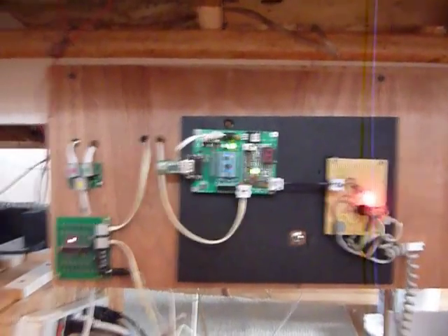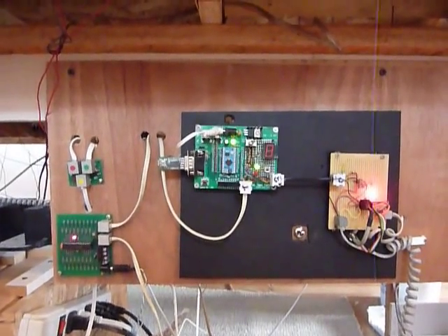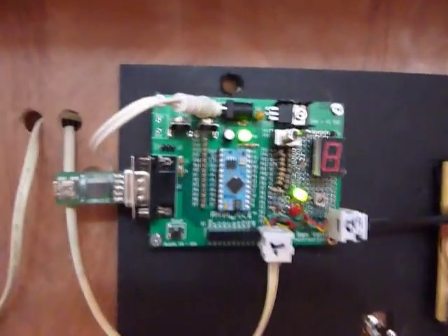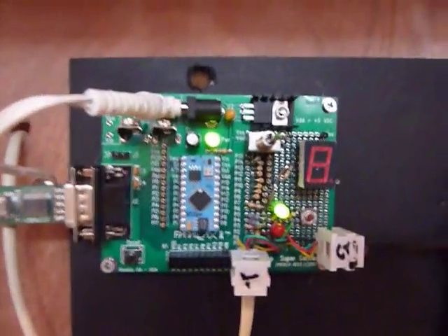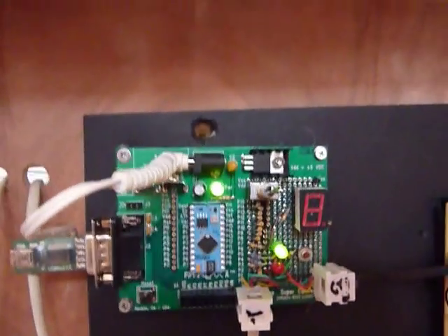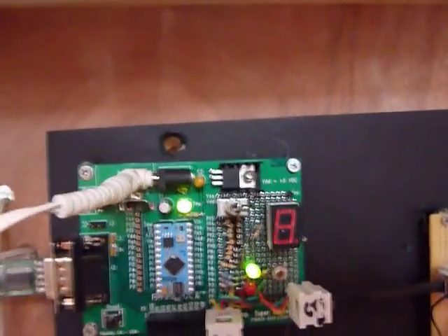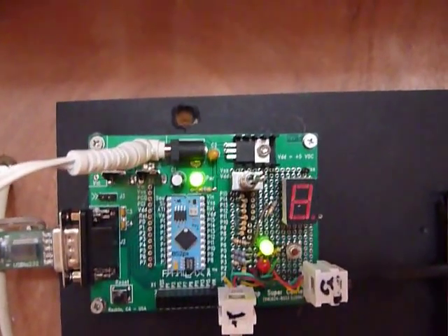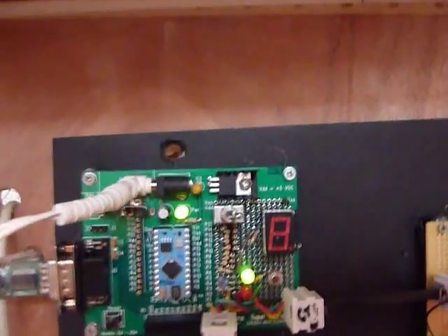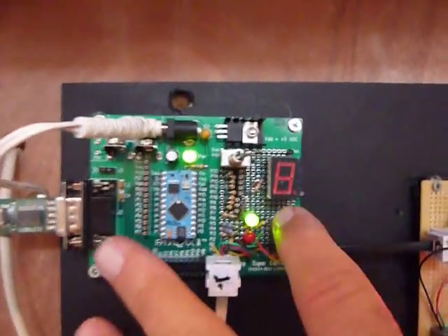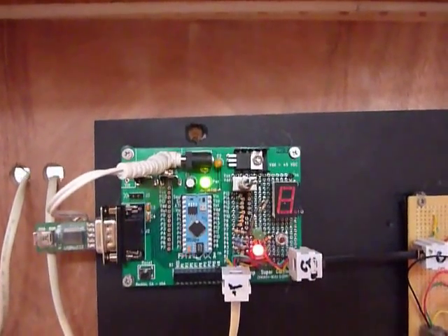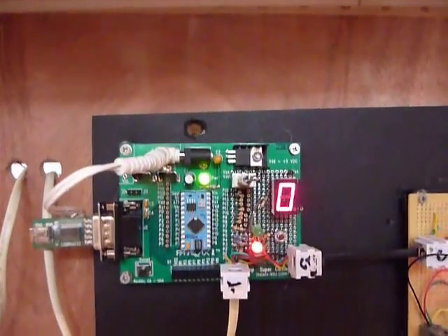Okay, this is a short video of the control system up and running. You can see here that the two green LED lights are on the stamp board. Right now this is in the run mode because there's green lights on, and the LCD, although it looks like it, it's actually the segmented LED, is not lit. Now I can force this device into the load mode by holding down this button right here that I've mounted, hitting the reset button, releasing, red light comes on, and the LED lights.